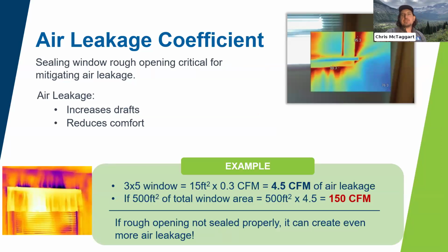I would say the air leakage coefficient that's rated by NFRC, that's not the only deal. It's also about the installation. So when my window installers were putting the product in, they started chinking in fiberglass around the rough opening. I said, you guys, that's fine if you want to do that, but you also have to seal it with foam. Why? Because I wanted to make sure that the windows were airtight on the outside.